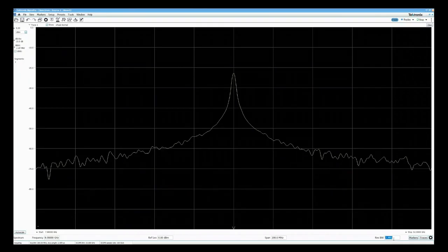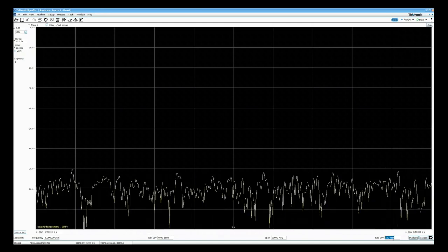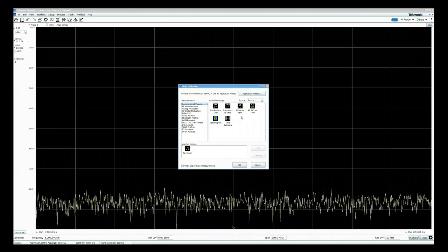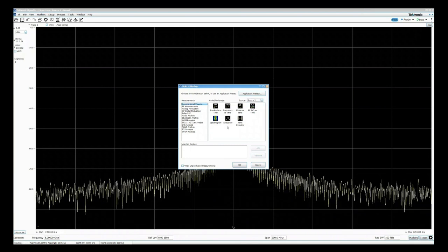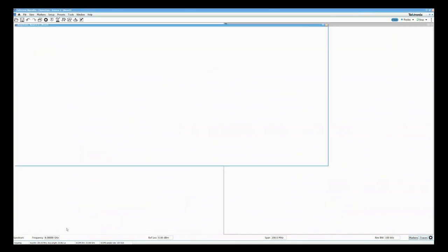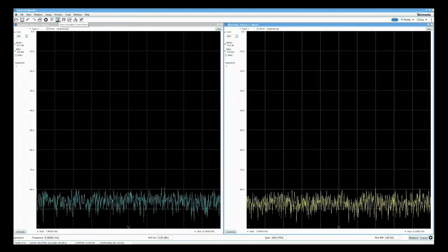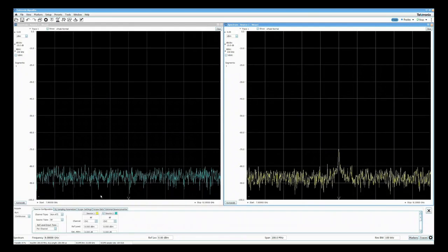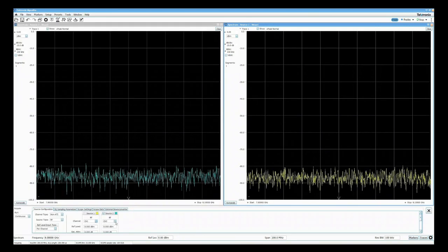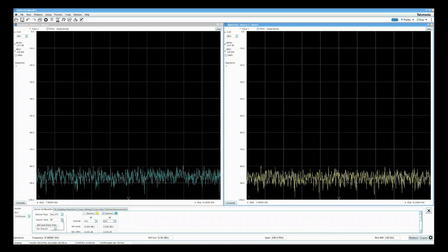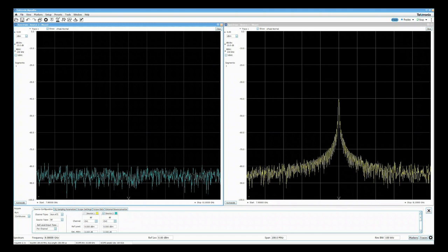Let's use SignalView to see whether the signals generated are aligned correctly to the assigned time slot or not. To do so, we'll set up SignalView to capture on both channels using the spectrum display. The source can be connected to any channel, math, or reference channel from the oscilloscope. This helps us in applying filters or performing complex operations before analyzing in SignalView. Additionally, the signals can be RF, IQ, or differential IQ pairs.